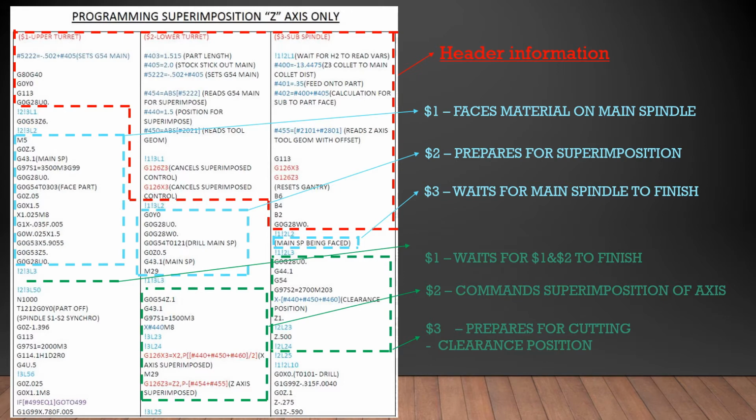Let's look at column 2 again and follow the programming. We have the G54, the drill moves into Z.1, 1500 RPM, M3, and we are now only communicating between channel 2 and channel 3.